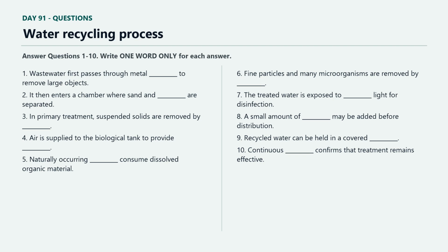The distribution network must also be protected from incorrect pipe connections. Where recycled water is not intended for drinking, color-coded pipes, signs, backflow devices, and inspections reduce cross-connection risk. The final part of the system is verification.